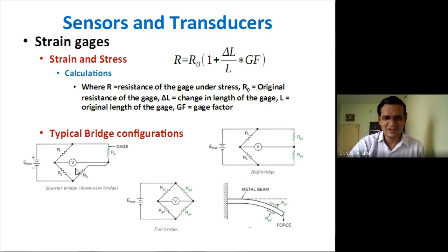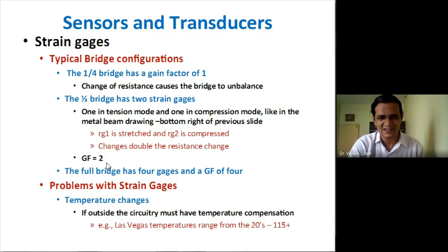So as and when you apply force on that material, changes occur in the wire length, in the cross-sectional area, etc. You can monitor and measure that. Effectively, the resistance will change. The change in the resistance will be monitored and maintained through the change in the output voltage. So this is how you can measure the mechanical force occurring at any muscle.